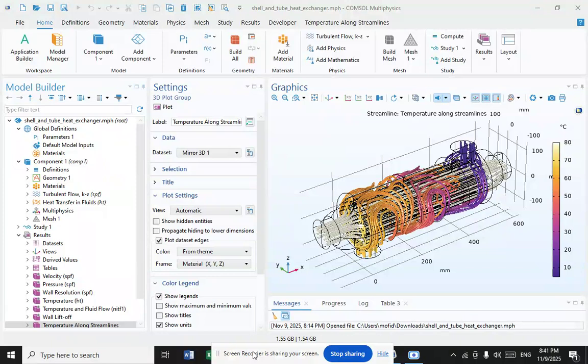The next is plate fin heat exchanger. This type of heat exchanger uses sandwich passages containing fins to increase the effectiveness of the unit. The designs include cross flow and counter flow, coupled with various fin configurations such as straight fins, offset fins, and wavy fins. Plate and fin heat exchangers are usually made of aluminum alloys, which provide high heat transfer efficiency.